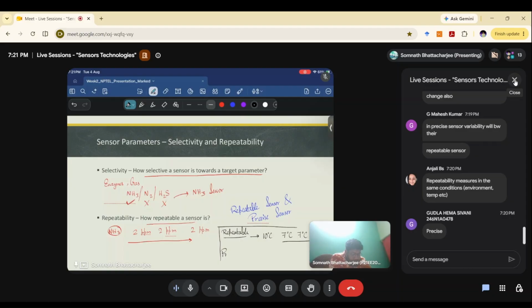Now, let's say if the device was something like this. So at 50.1 degree centigrade, the value is 20 millivolt. At 50.2 degrees centigrade, the value is 20.2 millivolts. So what is our resolution?